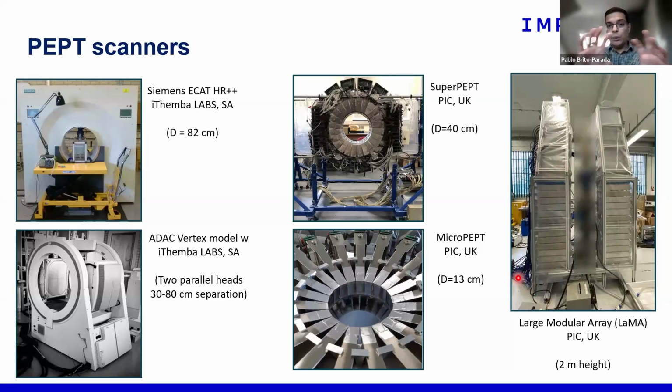In this case, we take the buckets, and then we can arrange the buckets and the sensors in whichever way we want. And that has been really useful for taller flotation cells, non-conventional or not mechanical flotation cells, but fluidized flotation machines. And I will show and discuss this application later in this talk. Much more to do as well. There are challenges when it comes to the size of the flotation cells that we would like to try, but particularly things like the modular array are opening the door to a lot more potential applications for flotation.